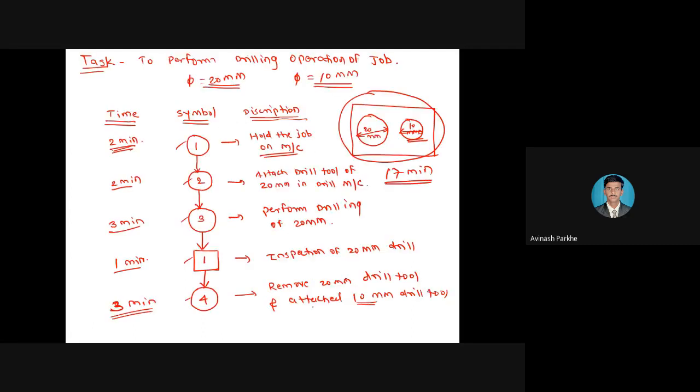So this is one sample problem I have just explained for your understanding. Like this, we perform so many operations. If you take the example of our lathe machine, in our day-to-day applications, we perform jobs on the lathe machine in your 3rd year. One simple circular rod is given to you, and you convert that rod into finished goods. Initially, you perform a facing operation to reduce the length.